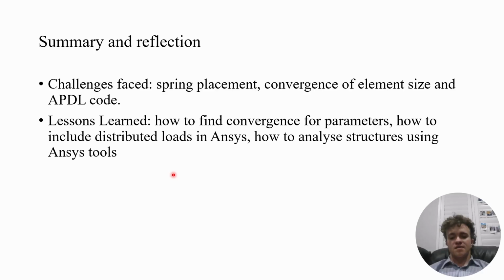So throughout this learning and this problem that we set out to solve, I had to make several assumptions in order to just get the ball rolling. We had to assume that the material properties were the same in every single direction. We had to assume that the supports could be modeled as hinge supports, and we also had to assume that all of the components were that structural steel material, which they were said to be.